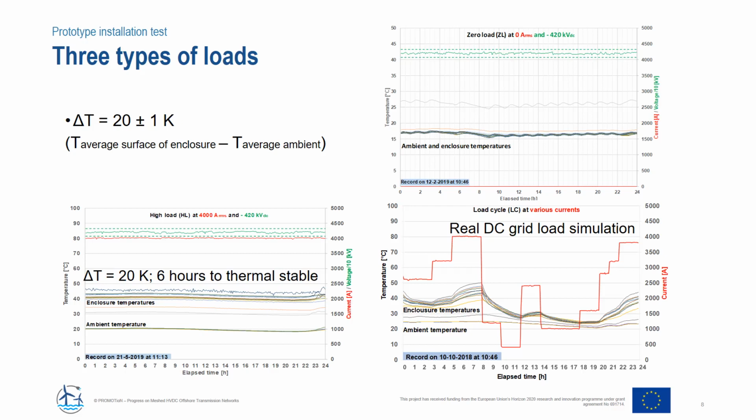One thing I did not mention is long-term DC voltage was chosen to be 420 kV. This is to compensate for the long-term aging effect of HVDC GIS under real application, because this test lasts for 1 year, but to compensate for long-term, the voltage has been increased by 20% more than the rated continuous voltage mentioned at the beginning.